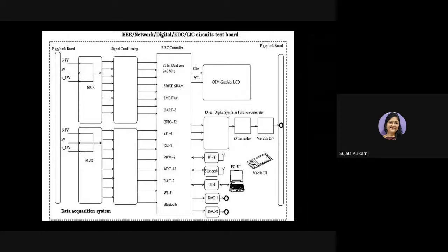Whenever students are using the board, strictly follow the operational manual and particularly make sure what operating voltages you are using, and before you make any connections, make sure the input voltage never ever exceeds the specified voltages, because once damaged means damaged.